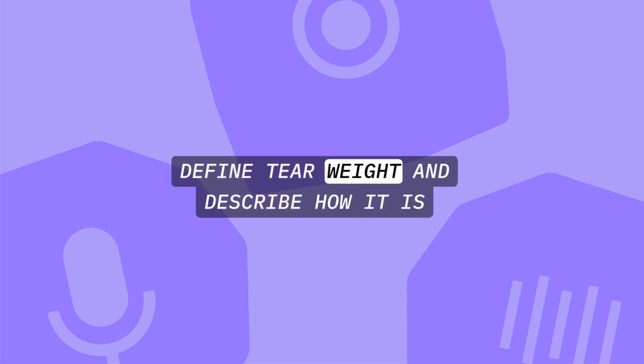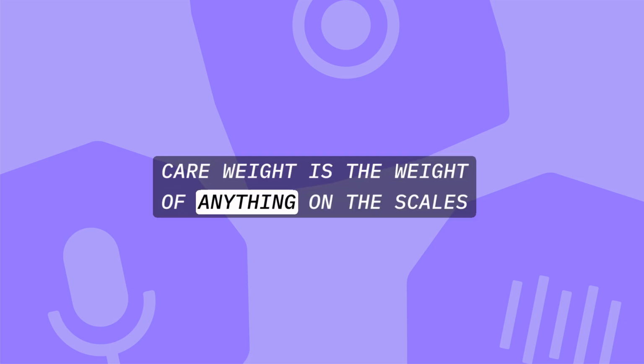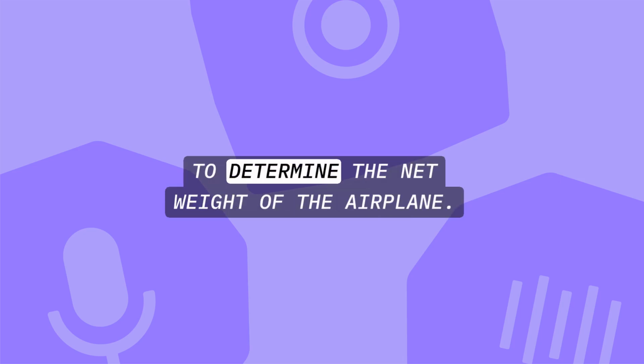Define tare weight, and describe how it is handled when weighing an aircraft. Tare weight is the weight of anything on the scales that is not part of the aircraft. It must be subtracted from the scale weight reading to determine the net weight of the airplane.